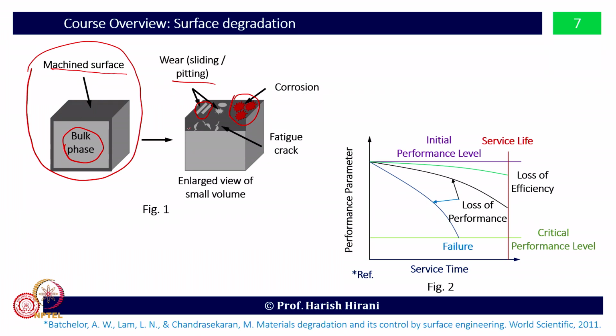Quite possibly, because of the just-below-surface layer, there is a possibility of an intermediate layer. Many times when we do a coating, we need to have an intermediate layer which can attach the coating with the main surface, or the substrate. That failure also may start, and the fatigue failure may start from that.